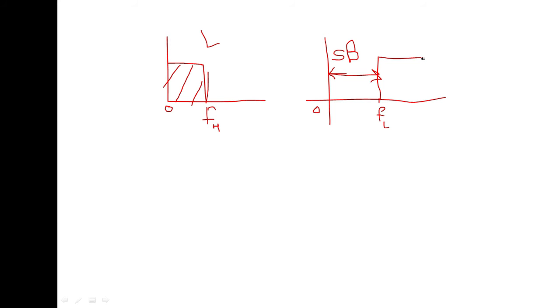Then once we combine both circuits, a particular band of frequency will be able to transmit. Means we combine the low pass filter as well as the high pass filter. This is the high pass filter. Once we combine the low pass filter and the high pass filter, we get the band pass filter. There is a BPF, band pass filter.